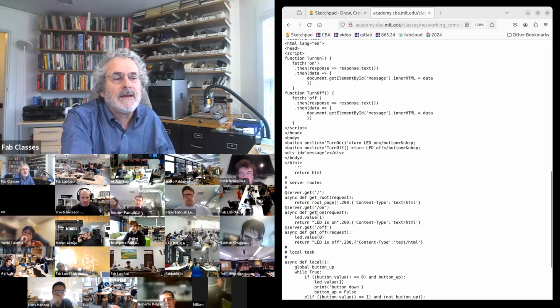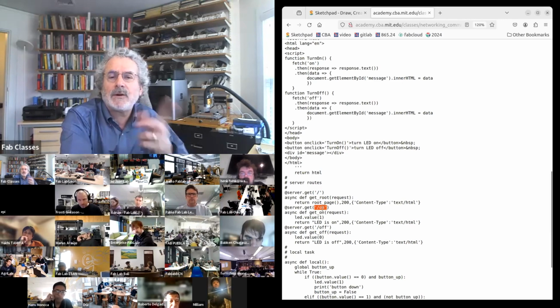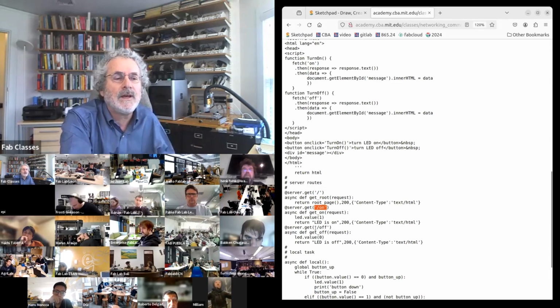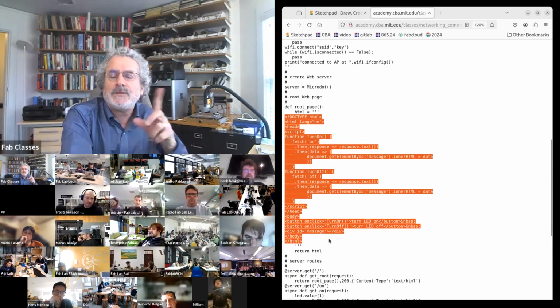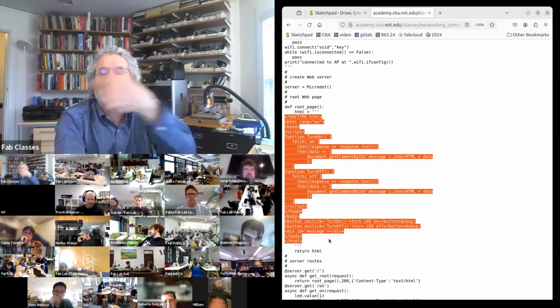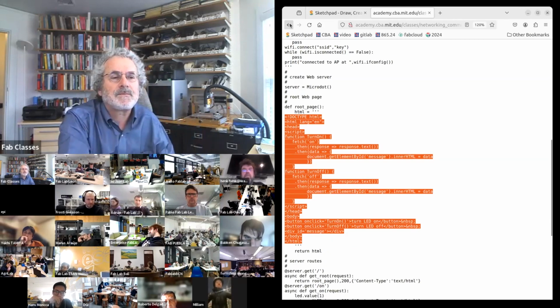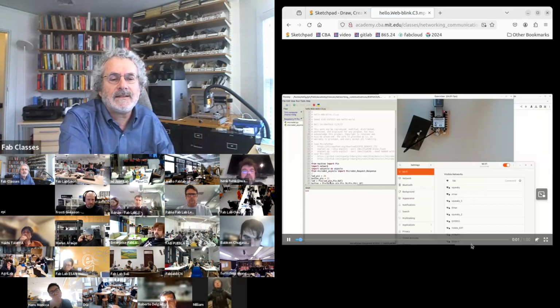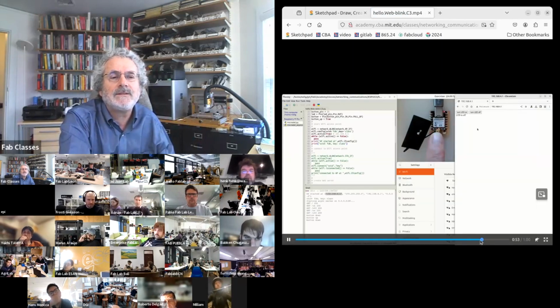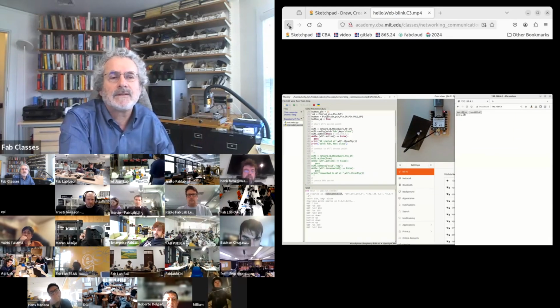And if I get the root request, I send my web page. And if I get a request to turn the light on, it turns the light on, and off turns the light off. And then this little bit is the HTML stored in the radio that I'm going to send to the client. And so all of that at the end lets me serve a web page from the Xiao and interact with it from a browser.